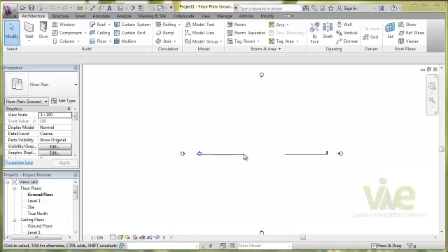So that being said, let's get started and see what we have to consider before we start modeling a topo surface. You may remember from our first lessons, where we started with a kickoff tutorial with Revit, that you first have to establish your levels. This is very important because this is a reference that you're going to use while you're modeling a topo surface. Secondly, if you want to get a net cut, net fill calculation, you must also have pre-established your building phases.